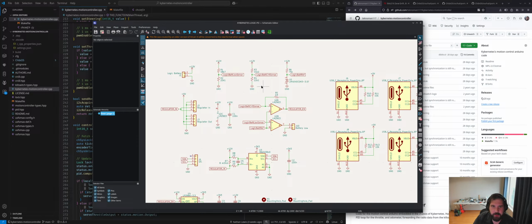So the reference voltage in this system is provided by this 3-volt Zener diode reference supply. If either of these drop below 3 volts output, then the signal throws. But this low sense triggers when the battery's at like 90% used, and then critical triggers at the minimum safe voltage on the cells. So the low sense has a GPIO output that can be read, and then the critical sense will shut down all the voltage regulators. It's a hardware protect feature.